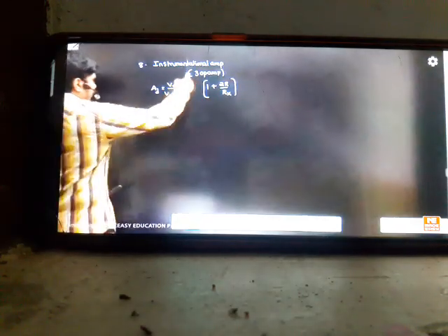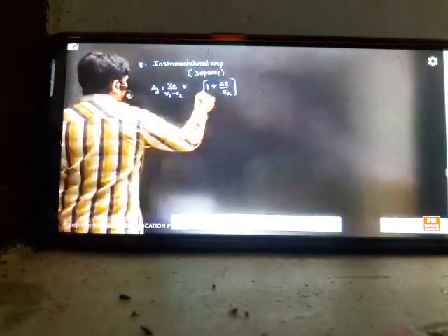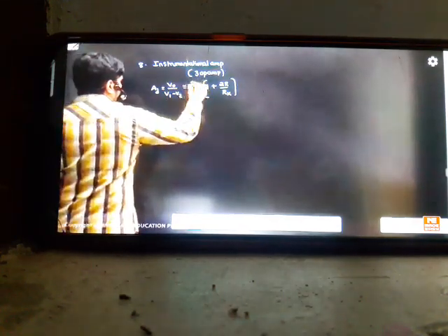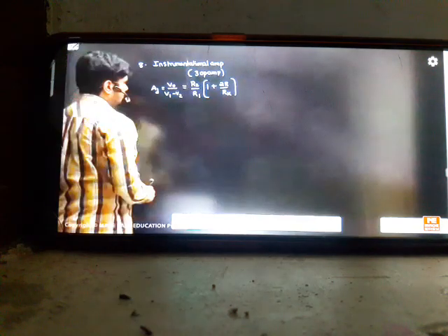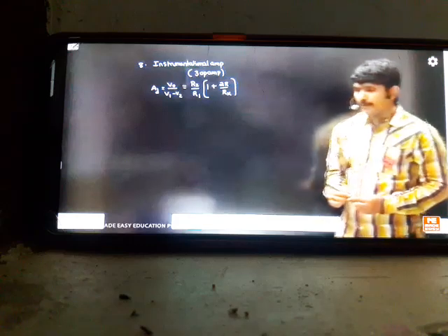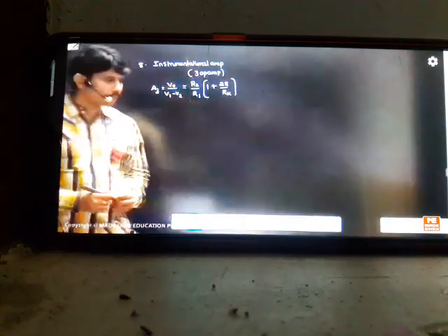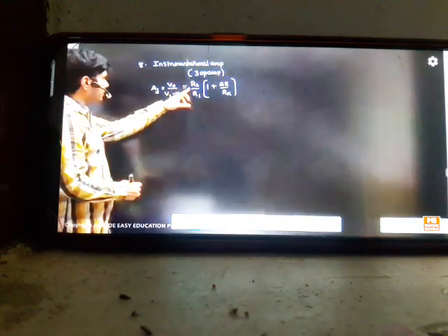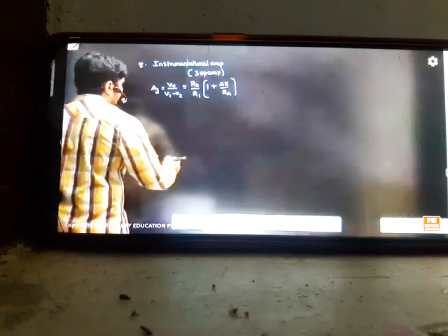1 plus 2R by Rx means 2 resistors are in series, and in the middle Rx is there. And we have this quantity, what we can write is your differential gain, that is R2 by R1. So this is the style. Your differential gain is R2 by R1. And we have 2 input non-inverting systems that give this quantity 1 plus 2R by Rx. Like this you can recollect the points without doing all the derivations. This is the differential gain, and this is due to the 2 op amp effect. 1 plus 2R by Rx, with Rx in the middle of 2 resistors.